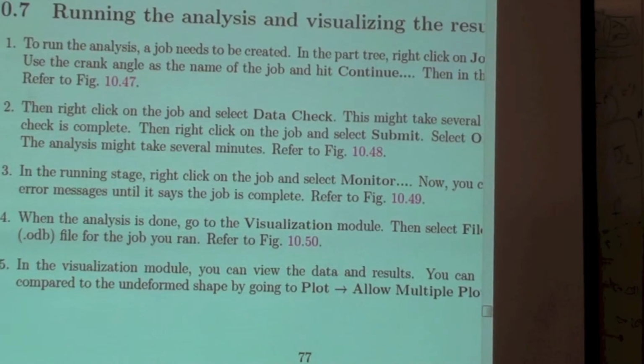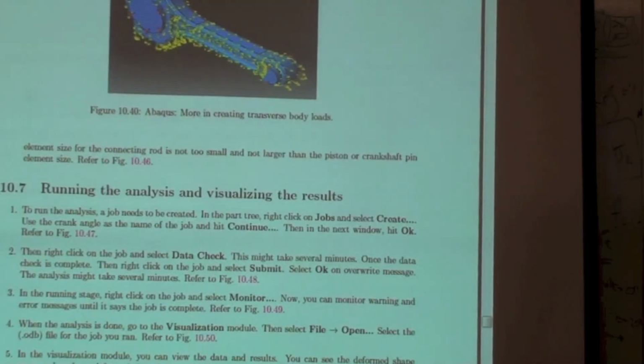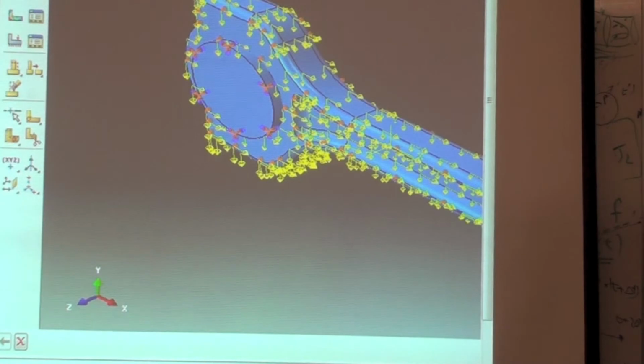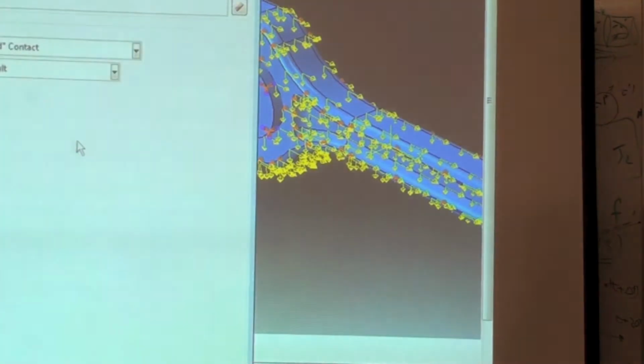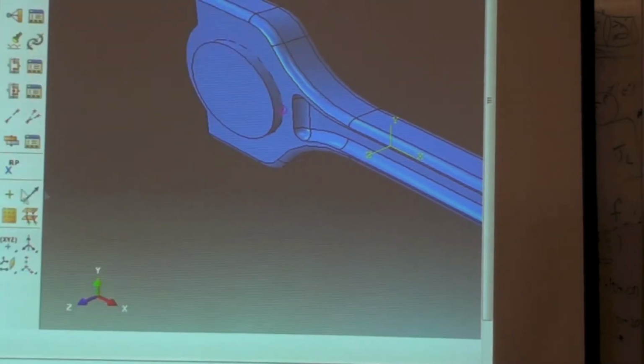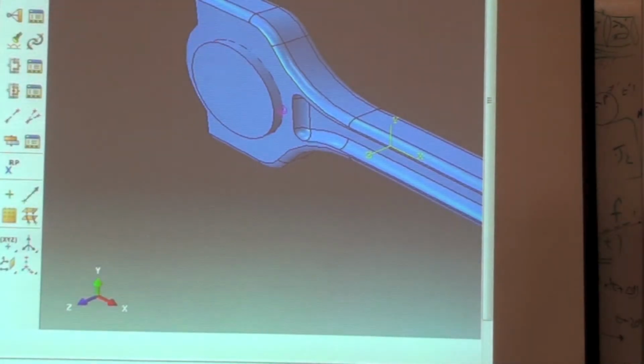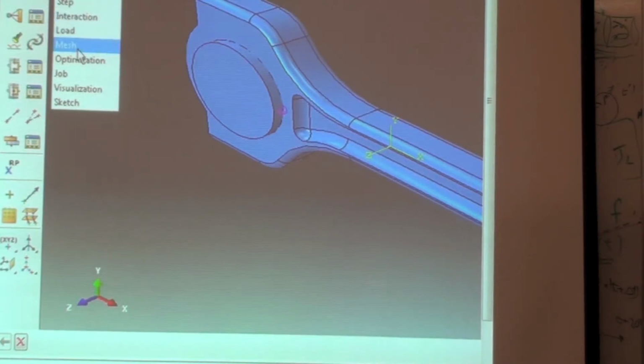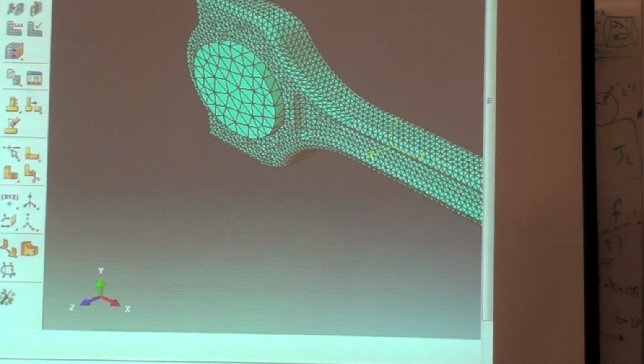So what is left? You set up the whole model with the loading conditions, your boundary conditions, and the interaction properties, like a contact property. I'm setting up a normal contact property, and if you follow the tutorial, it sets up everything. Then you have to make sure there are small sliding interactions and stuff. So the final thing, once this is all set up and you've gone through the loading, is the mesh. Then you have to mesh these elements.